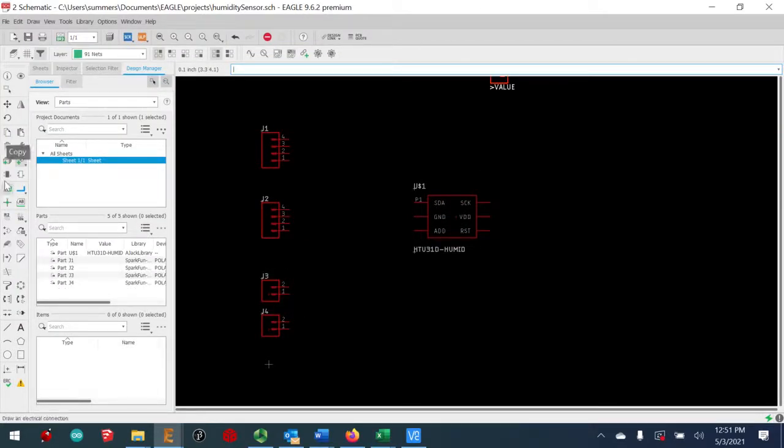Okay, so now we are going to go to Net, and we're going to put these things together. So I want this first two headers to connect. So one will be like for input and the other one will be like for output. And we need to have a ground for all of these. So I'm going to connect the number 1 pin for the grounds for each of those to the ground. This guy here is just going to go from one header to the next. So that part is done.